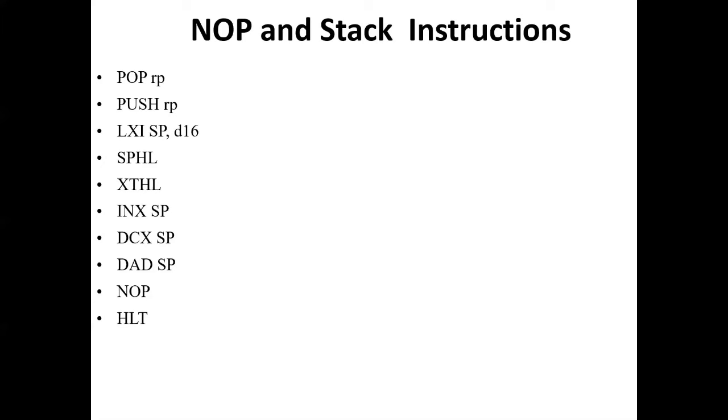Let us say SP contents are FC78H and we want to read information from a stack location. In this case, we are not interested in reading from a location whose address is less than the memory address present in SP. This is because 8085 interprets them as useless information. So we can load the register pair BC when SP contents was FC78H.